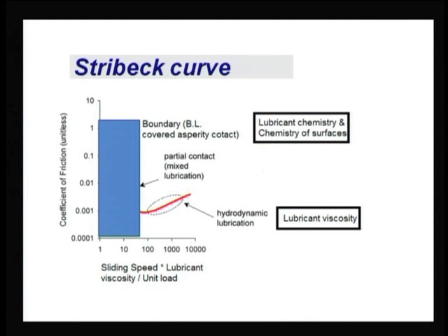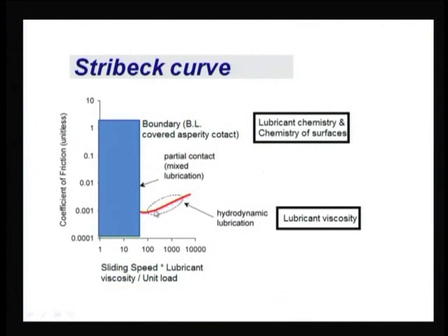Now, because of the heat, temperature will increase, and because of the increase in temperature, the separation between molecules will increase. That is going to cause a lesser viscosity. That means, if we started from a point here, it will decrease. Because of lesser viscosity, the bearing number will decrease and then the coefficient of friction will decrease. As the coefficient of friction is decreasing, naturally heat generation will decrease. That is why the heat generation will be decreasing, that will lower the temperature.